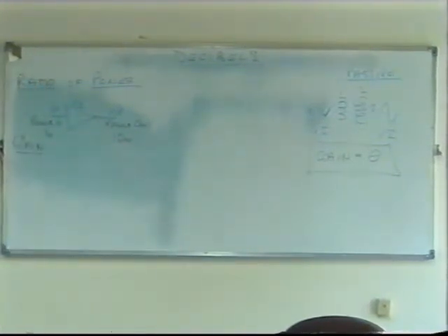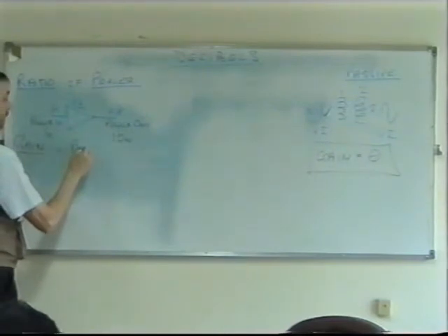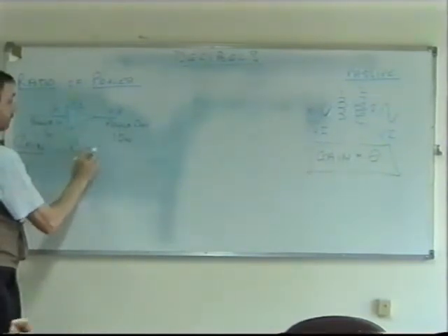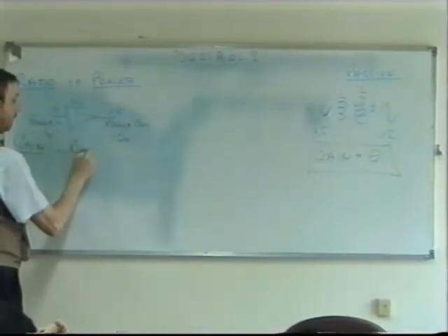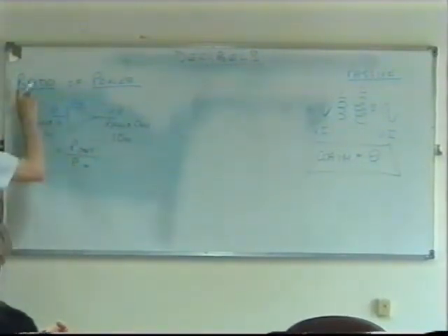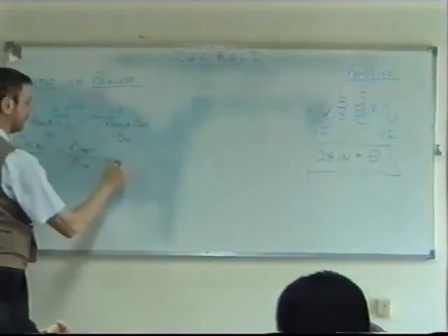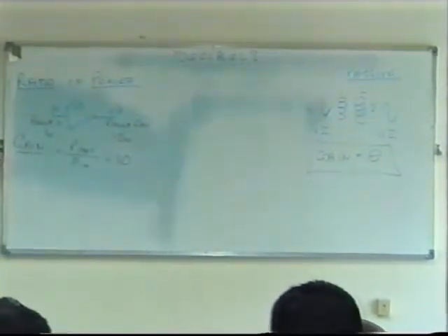Power. Now this is power, not voltage, not current. We don't know what the current and voltage is, that could be anything. We can actually use a transformer at the output to change the ratio to anything we want. Again, 10 divided by 1. Yes. Now here we can talk about gain as equaling power out over power in, can't we? As a ratio of the two. Here we're using the ratio, so therefore we would say in this case the gain is about 10, isn't it? Because we've got 10 times more power coming out of the device.